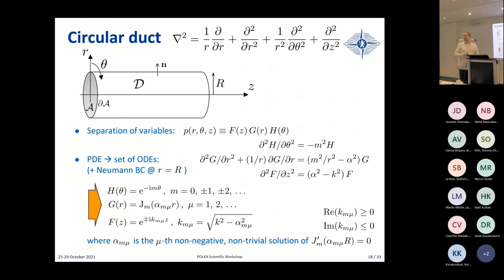Any other question? Yep. About the evanescence of the modes below the cutoff frequency. So you're saying that in those scenarios you neglect those modes, right? Yeah, with some caveats, but yeah. If you have a particular solution, so you have a response at that frequency, it's higher than the decay, yeah, not continually excited. The problem is that the rate of decay depends on how far you are from the cutoff frequency. If you are just below the cutoff frequency, your mode will be exponentially decaying, but with a very small negative exponent.